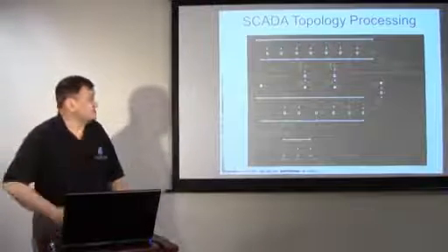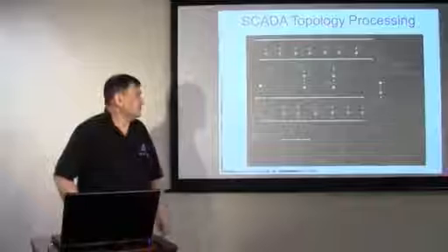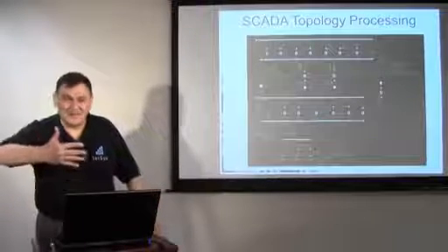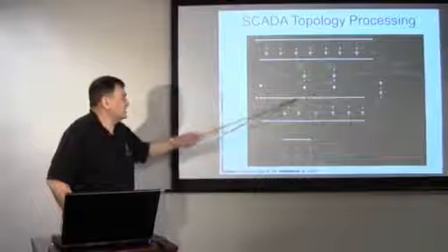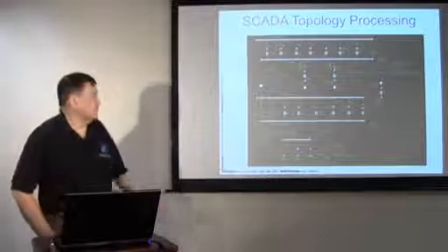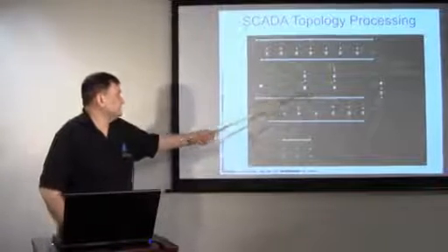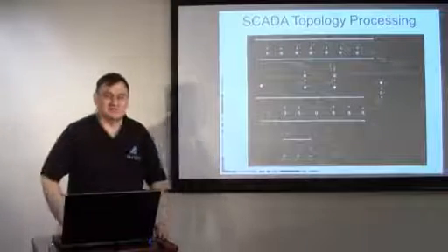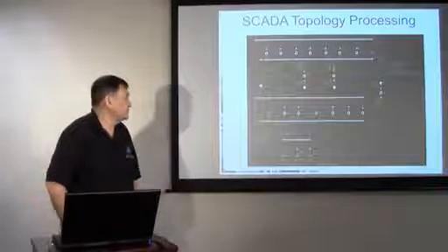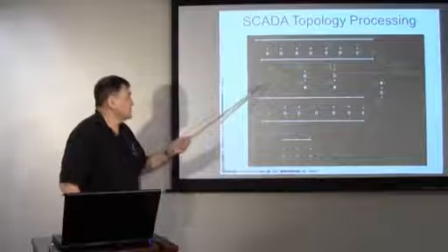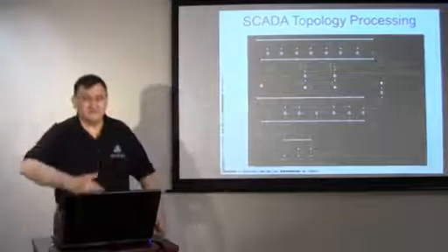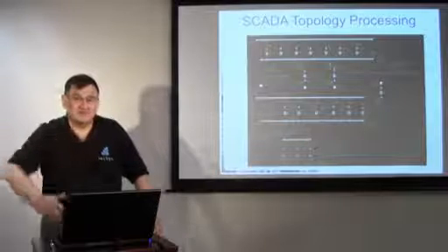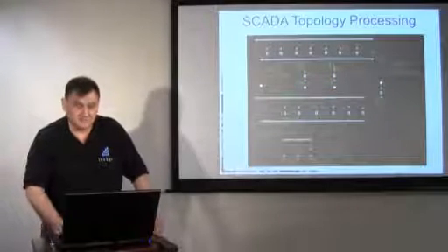So if an operator should see this, the initial reaction is, well, my RTU's gone bad, but in real life, this is a very common, very severe type of fault, where the fault is on one bus, the breaker is closed, so the other bus is also cleared as well. And then, of course, there's a whole procedure to rack out the faulted breaker and start restoring everything to service. But again, this shows the benefit of modeling down to the lower voltage levels for training purposes.